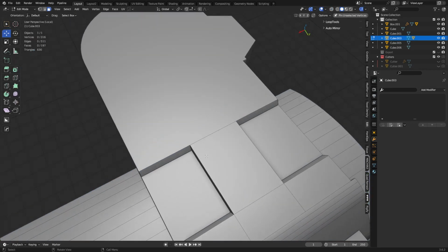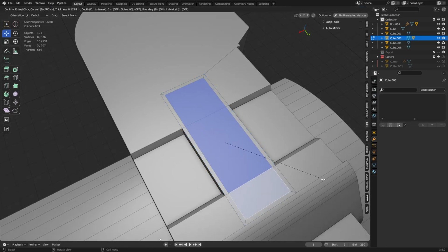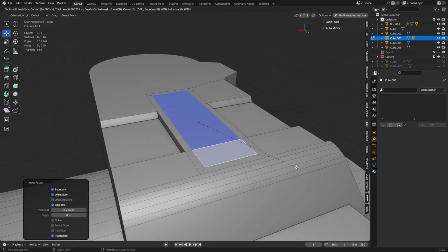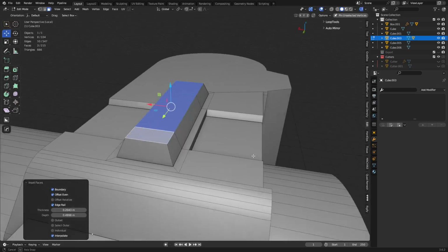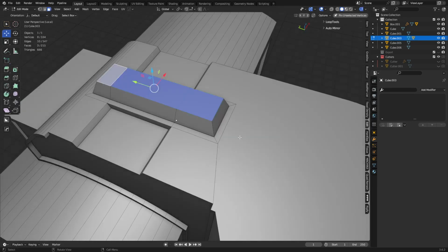If I want to do a square cut here, this is kind of hard to do actually, now that I think about it. But I could do like knife tool on Y, and then on X. I'm going to overextend it. I'm going to go down here. I'm going to hit Y again, cut to there. So I can dissolve that little vertex, grab this whole area, inset it. So hit I, inset, and then inset again and hold control. And maybe just let it go for a sec and do that number. So we can do some detail in that way as well.